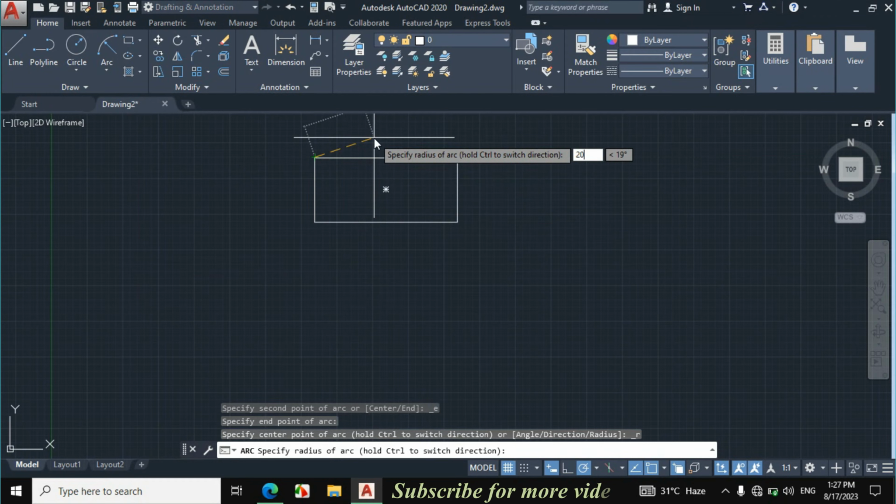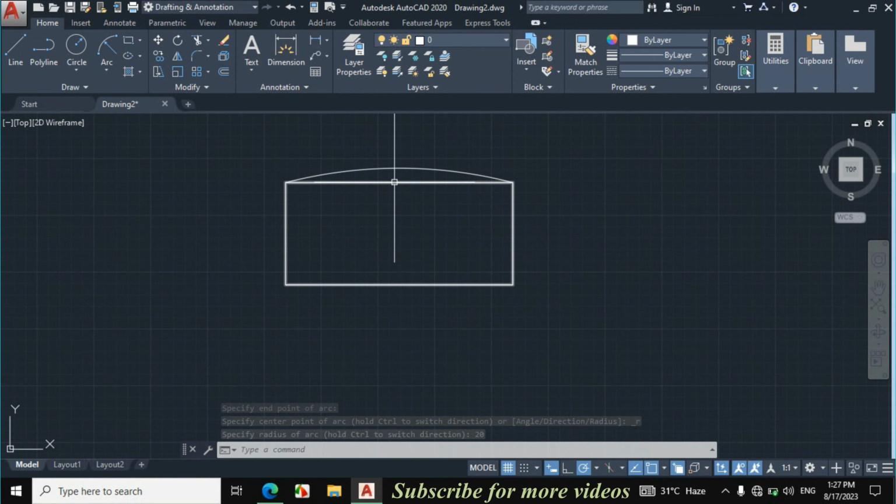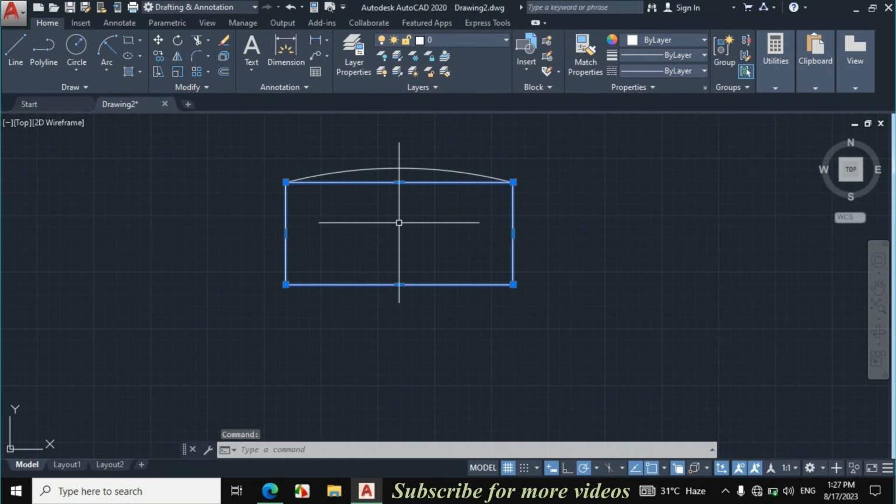Enter radius 20 mm. So first I will explode the rectangle, then I will erase this line. Select the rectangle, enter X from the keyboard to explode it. Now select this line and erase it.